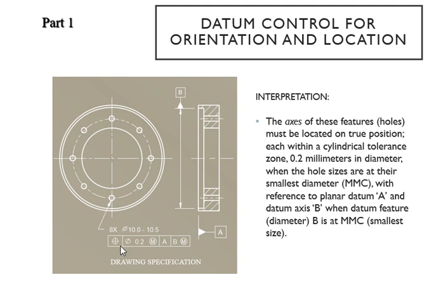Of course, in this example, we know that it is millimeters right away because you can see the zero right in front of the decimal. I'm not just reading this, we're reading this, okay? So in this control frame right here, when you look at it, you spot the two datums here, the primary and secondary. And you spot them in your drawing. You can see right here and here they are, the surfaces or plane.